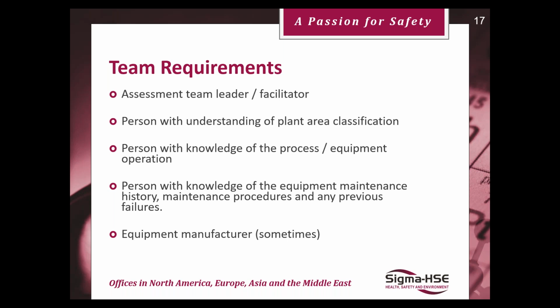So in this specific example, I want to recommend for this reactor, this agitator, to undertake maybe more pressure drift testing, like a pressure testing of equipment before each batch, just to make sure the bearing isn't being destroyed or deformed. So it really helps having that knowledge of the equipment, especially from the person handling it.